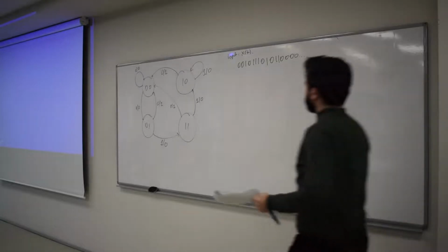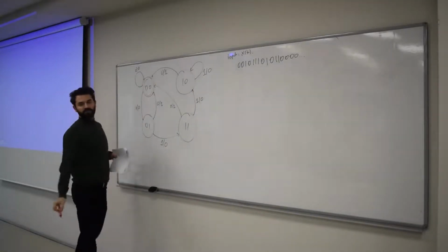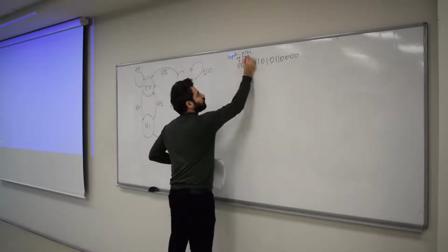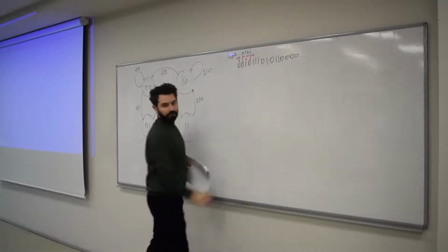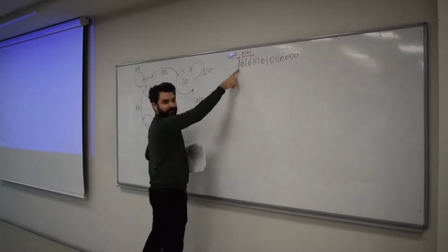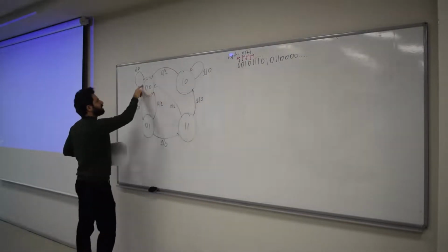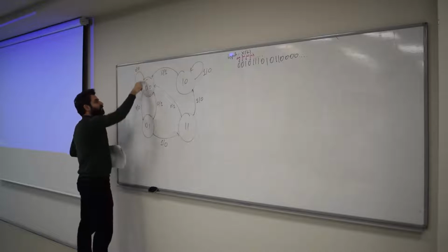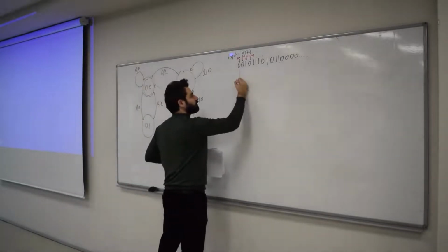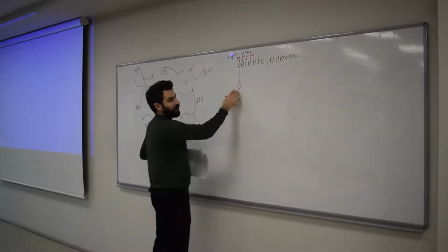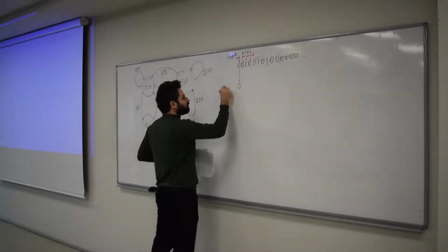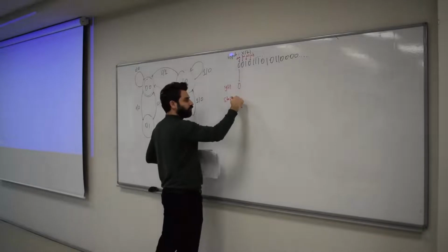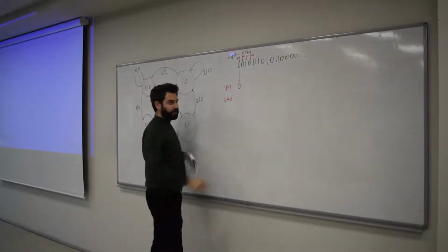Okay, so what's happening here? So I'm actually in this state at t equals 0, let's say. So this is my t equals 0, okay? This is my t equals 1. This is t equals 2. T equals 3, and so on. So at that particular moment, t equals 0, I have a 0 in the inputs, okay? That means, since this circuit says that if you have an input 0, push out a y 0 and you stay in the same state. So I'm going to push out a y, so that would generate a 0, output 0. But I have to keep the state, right? So I'm going to also have, this is yt, and this is state. Okay? Since I've got 2 bits for the state, I'm going to put 2 bits on top of each other, all right? To represent the state.